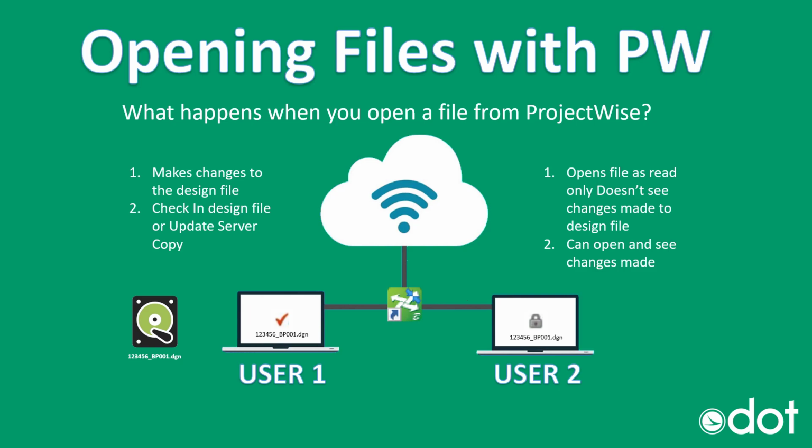All the files are stored within the ProjectWise Work Explorer cloud, and when you've opened up ProjectWise Explorer, you can check in and out of files. User 1 has checked out the BP001 file, and it indicates to them, the user, that red check mark. In that process, when you've checked that out, it is downloading that file and all the other associated files to your working directory on the hard drive, as you can see. Once that is loaded, you can make those changes to the document.